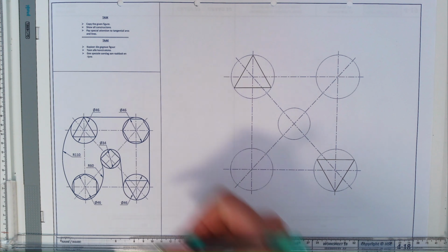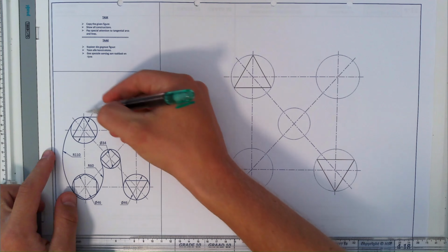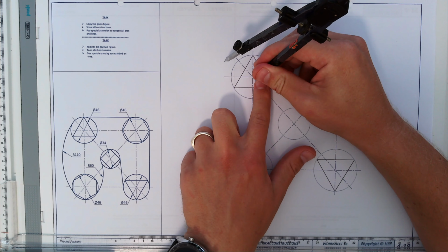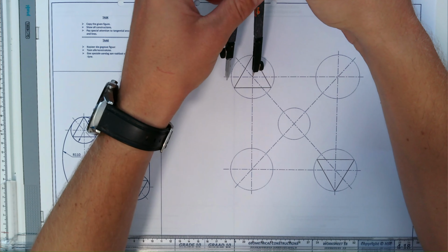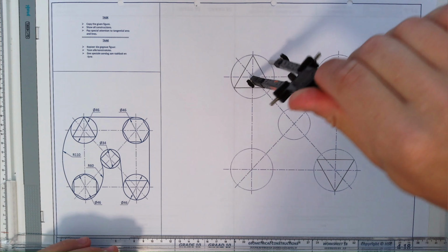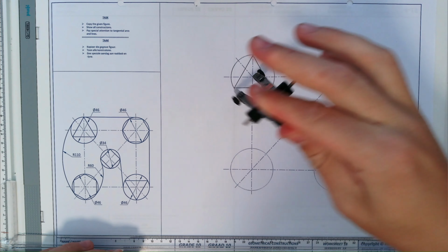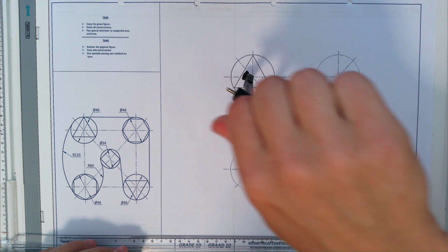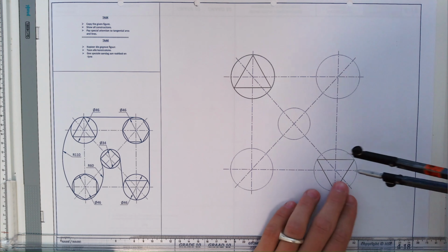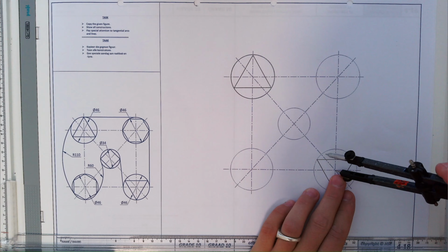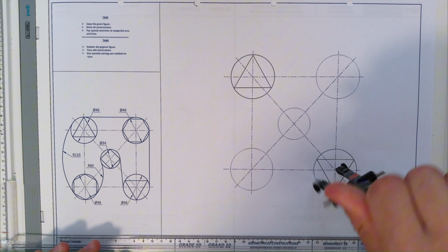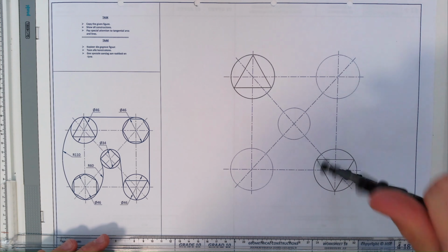We can also see that both of these circles are solid circles. So I'm going to do that. You put your sharp point of your compass in the middle. Take the lead to that edge of the circle. And now we're just going to darken that circle. We're basically making that circle ours. Happy with that. The same down here. Sharp point in the middle. Take the lead to the edge of the circle, and make it a solid circle.